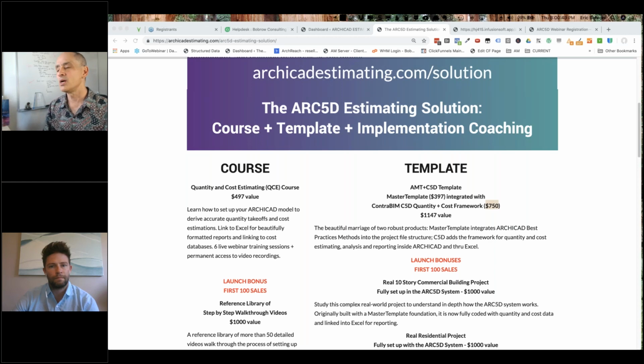Well, as far as I know, ArchiCAD does a very beautiful model revision when you subtract one thing from another, and the estimate is going to be based on that data. So you'll have an accurate amount of concrete, for example. Now you have to accommodate for wastage or other things. So if you're talking about taking a groove out of a wall, maybe that concrete is wasted or maybe not, depending on how your fabrication is done.